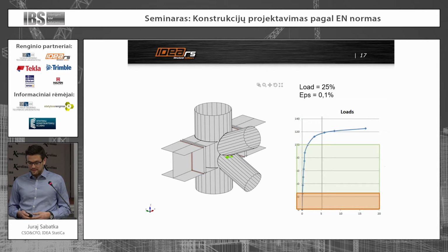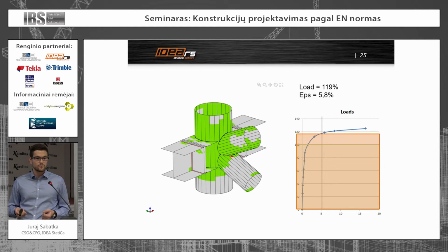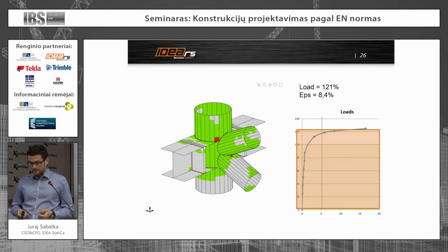And what is important is that the software is not a black box. In every stage of the modeling, you know where you are, and we will show this on the connection itself in relation to the material diagram. We will be gradually loading the connection, and the goal is to see exactly when and where we reach limits, what the plastification zones are, and where exactly the connection fails.